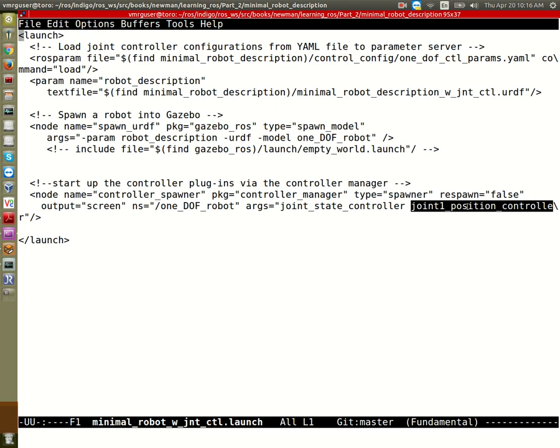Sometimes we will have position controllers, velocity controllers, effort controllers. And sometimes you'll have them for each joint. So Baxter has 7, right? So you need to put a list of 7 controllers, maybe plus the joint state. Yeah? This list can get very long. You can compare this to Baxter files, for those of you that have some experience, to see how this looks for a more complicated robot.